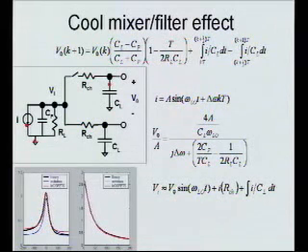However, I do think the other thing is, historically, active mixers have been popular for a very long time because you can't do passive mixers with BJTs. It's impossible. They have no triode state. They just go crappy when you try to do that. So I think part of the reason that active mixers are popular is they're just historically popular, and passive mixers have only been really practical since FETs got fast enough, which is like the last 3 to 5 years. So there's been less time for that development.